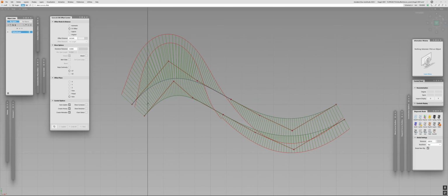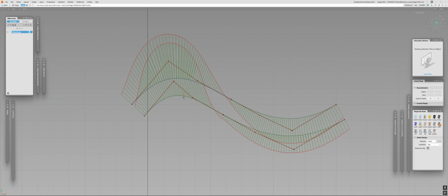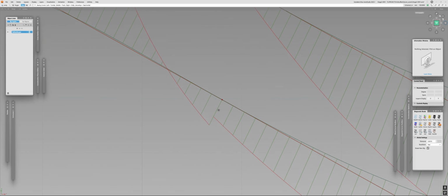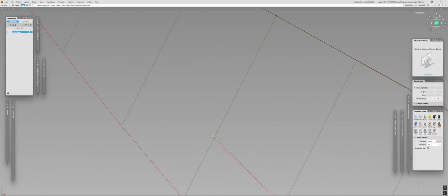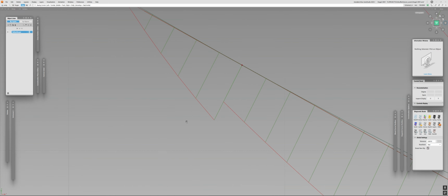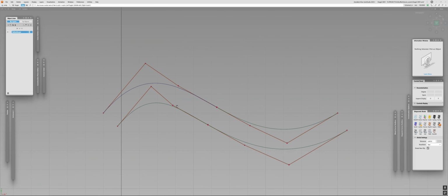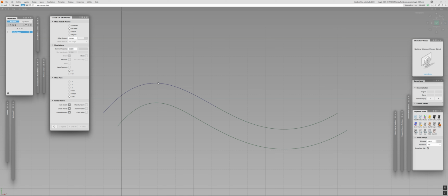You're going to see that now our curves are very accurate and smooth. They have actually the same parameterization as the original one, but they lack the continuity even more. So you're going to see there is a huge gap in curvature now, and a really small one in tangency. Once again, we're failing both curvature and tangency, but at least here we have a good curve. But if you look closer with this method, it is actually visible by eye that the distances are not equal.